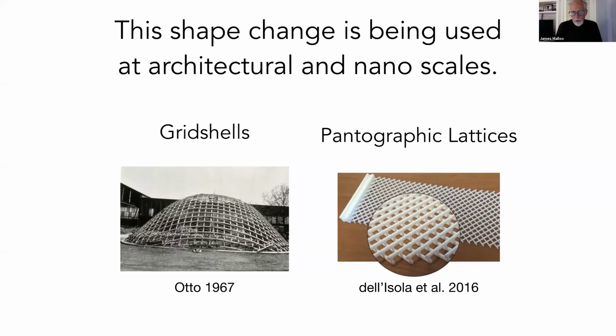A grid shell is typically lifted up, or maybe pushed up by inflation from the bottom, and then the edges of the grid shell are restrained. At that point, you have something like a straw hat that is a definite shape, but it's still sensitive to asymmetric loading. A point loading would make it, as you would expect from a straw hat, start to buckle in and maybe buckle out at distant points.